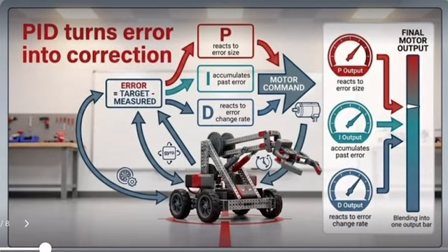So basically what that means is if your robot is swinging a little, I is gonna make sure it's not swinging at all, side to side. D reacts to the error change rate. What that means is how high your error is changing. So let's say your robot accidentally swerved a lot, the D would make sure it stayed on the path.